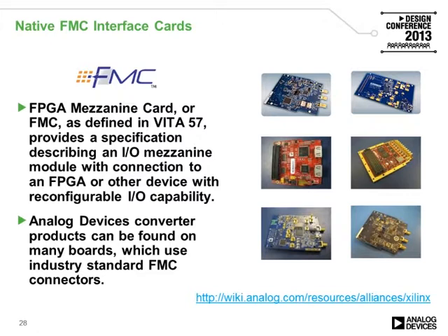The 9739A FMC board is a 14-bit 2.5 gigasample high-performance RF DAC capable of synthesizing wideband signals from DC up to 3 GHz. The AD-FMCOMMS1-EBZ is an analog front-end hardware platform that addresses a broad range of research, academic, industrial and defense applications. The AD-FMCOMMS1-EBZ enables RF applications from 400 MHz to 4 GHz. The AD9265 FMC board is based on the AD9265, which is a 16-bit 125 megasample analog to digital converter.